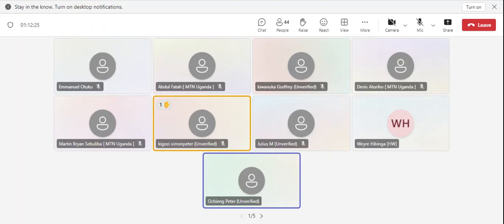Why I'm asking this is for you to give us the dangerous wavelengths, because the common ones we use are 1310, 1550, then 1625. Sometimes we get support from members who could not be in this meeting now, such that I advise the person to always set his OTDR on a particular wavelength that may not cause damage to these equipments. So I wanted the wavelengths that can be recommended that cannot cause damage, and the other ones that we may avoid. Thank you.